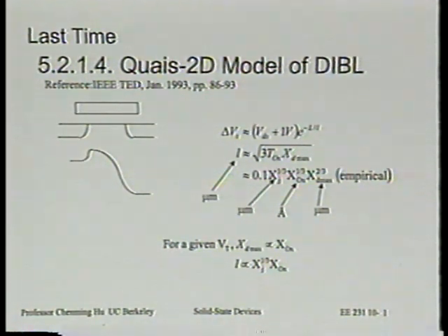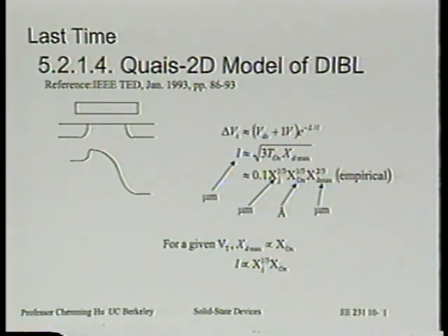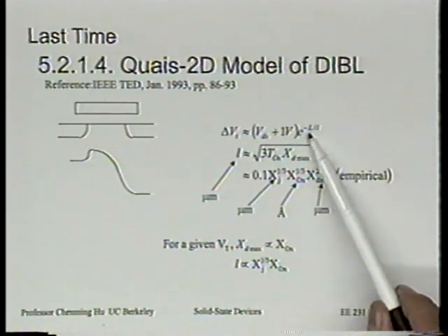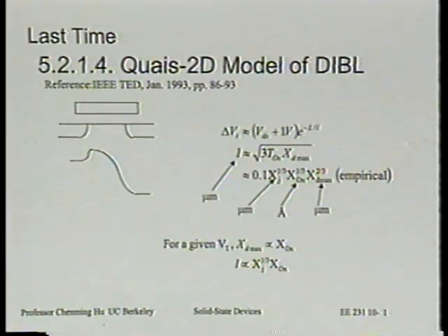Now it's interesting, if you put the typical numbers into these 2 formulas, they don't differ that much. Certainly it's within the kind of, say, even the experimental error that you can determine just by casually looking at the data between delta VT and channel length. From that data, you can estimate L, this decay length, right? Feel free to use either formula, and the bottom formula is probably more accurate because it has been obtained by looking at actual data and looking at simulation results. Is that okay? All right.